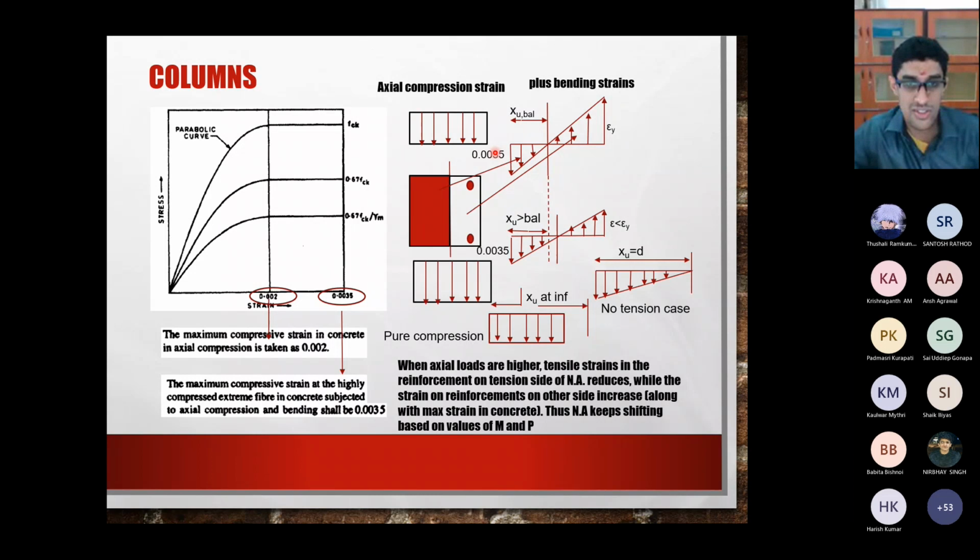It becomes taller. It becomes larger and larger, so the value of these compressive stresses becomes more and more. What you should notice is that compressive forces will add with compressive forces, and compressive forces will be subtracted by tensile stresses, not forces, stresses. As this rectangle becomes larger and larger and I combine it with this picture, this side will keep getting larger and larger and this will become smaller and smaller, because this is adding on to this.